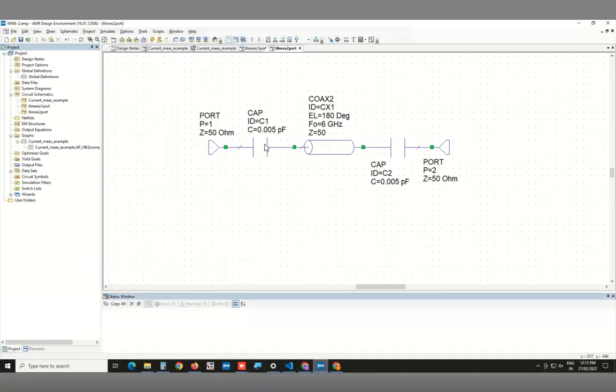Right? Because earlier also I said that this very small capacitance is like a weakly transmitting mirror. This is now 2 mirrors, both of which are weakly transmitting, right? So you can have energy leaking out of both directions, but still these are both voltage antinodes on either side, or current nodes. So it's a half wave resonator.